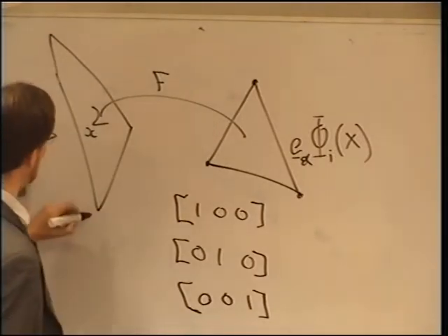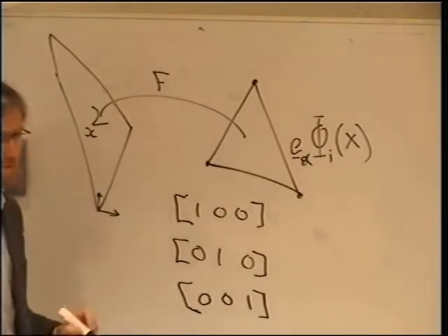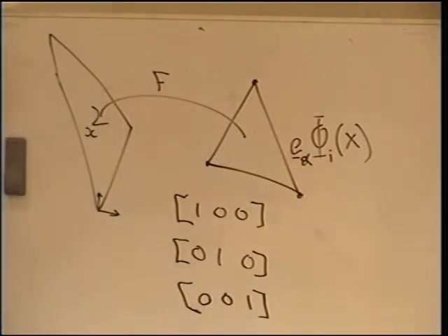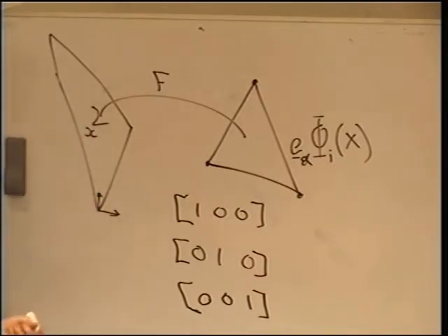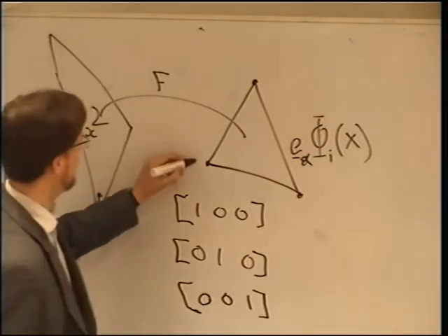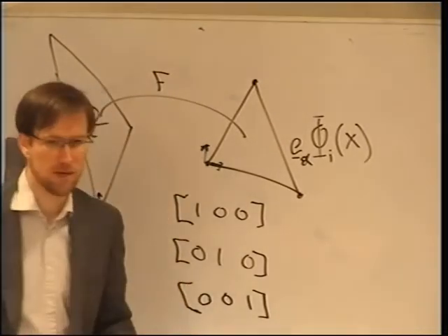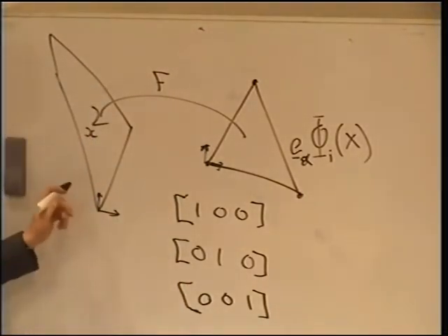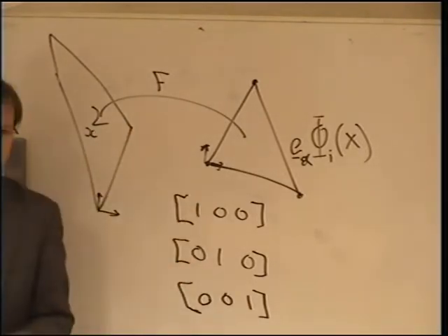So the vector values over here are with respect to the traditional basis, and that basis does not change for whatever shape this element is. It doesn't matter which way up the element is, it doesn't matter whether the element is bendy or not bendy, it doesn't matter how squished it is, the vectors are the same. And so that is great because it means that when we change coordinates from one space to the other, we don't have to do anything to our vector values.